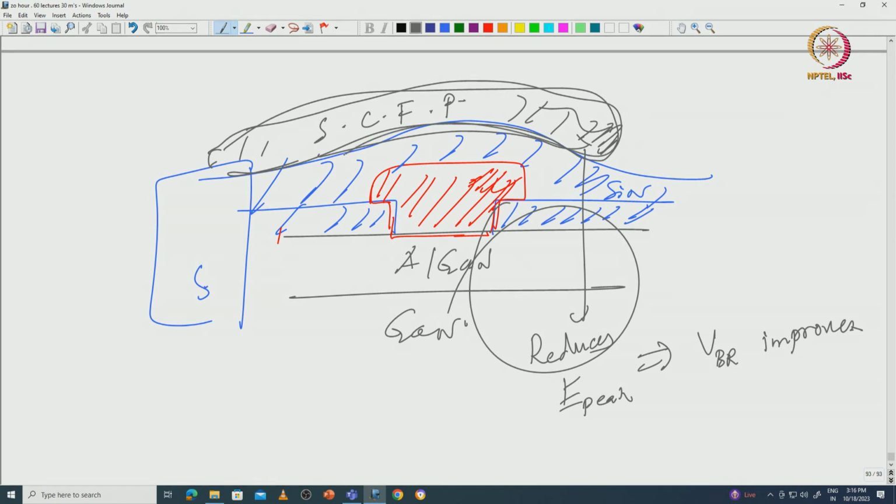Again, in the top view, if you have a source like that and you have a gate finger like that, then you can open the source here and here, and the source can, for instance, feed in a metal line like that, and then the metal could go like that. So there is a field plate and there is a metallic short here connecting. You do not want everything to be connected, because it will increase the capacitance, you only have this.